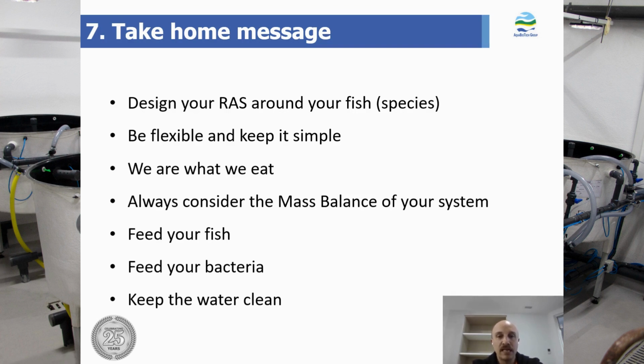Always consider the mass balance of your system, because this is the only way you have to make sure that your system is sized correctly. It's the only way you have to understand what happened to the metabolites produced by your fish, and it's the only way you have to predict what will happen to your fish if something goes wrong. Feed your fish, which seems quite straightforward, but also feed your bacteria, because without your bacteria, your biofilter will not convert and remove metabolites, and your fish may end up dying.